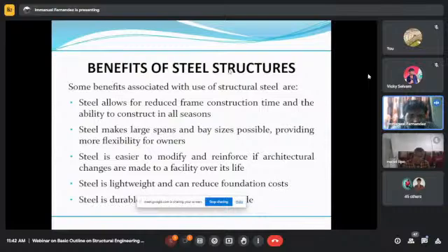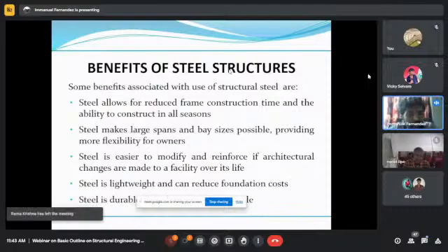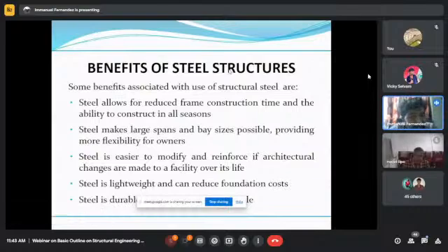The use of steel structures is like the construction time will be very less because what we do is we order, we do the design, and we give the drawings to the fabricator. The fabricator designs the connections using Tekla, and they send us for our review. We have our standards. Based on that, they will design the connections, they will prepare the fabrication drawings, and send us for our review. We will review the fabrication drawings and give the go ahead, and after that, it will be fabricated. Nowadays, we have modular construction. Modular construction in the sense like the piping, the structure, the equipment, everything comes as a module. The only thing at site is to bring the module and do the erection at the site. No need of separate components. Like before, we would bring the structural components, then we bring the piping, then we bring the equipment, and erection would be at the site. Nowadays, a single component will come, and the whole module will be erected at the site.